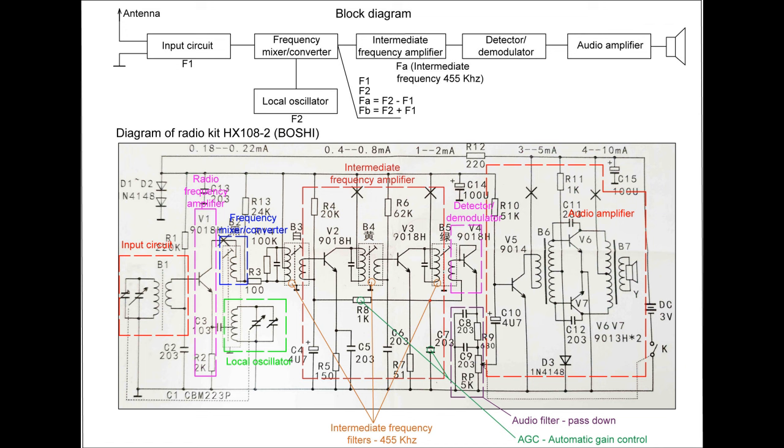Of these, we are only interested in the lowest frequency, respectively the difference between the frequencies, that of the radio station and that generated by the local oscillator. Thus, the frequency of the input signal is translated into a fixed frequency, called the intermediate frequency. The frequency of the local oscillator is varied in such a way that for any selected input frequency, through the input circuit, a constant frequency results at the output of the mixer.